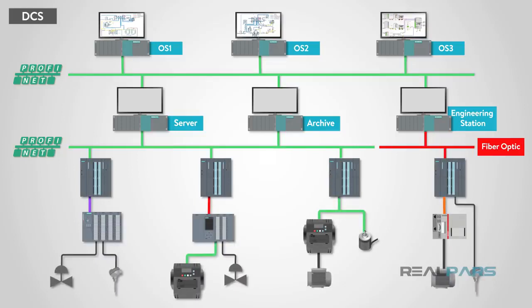Communications between this level and the processor level can be nearly any type that may be compatible with the components. Those include Industrial Ethernet, Profibus DP, EtherCAT, fiber optic, or other proprietary communication protocols. Components at this level would be devices such as transmitters, switches, valves, motors, remote or distributed I/O, etc.